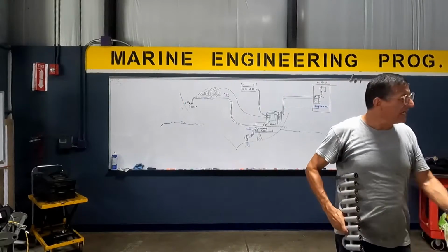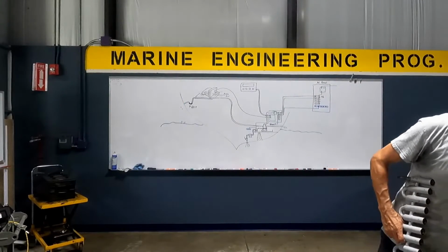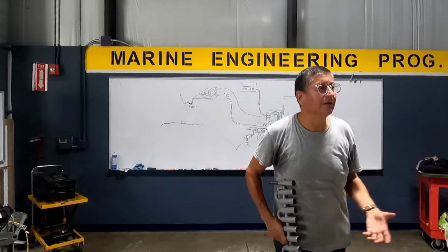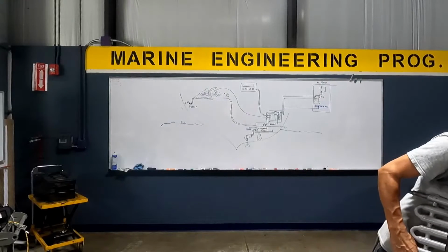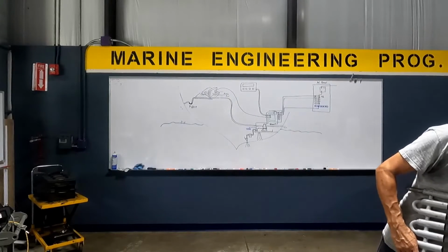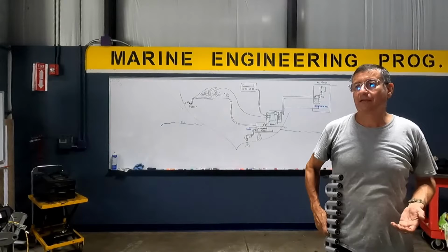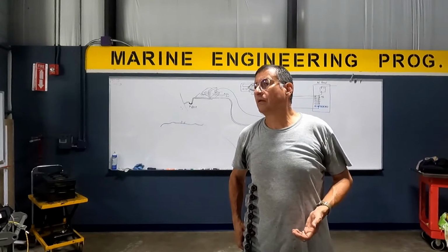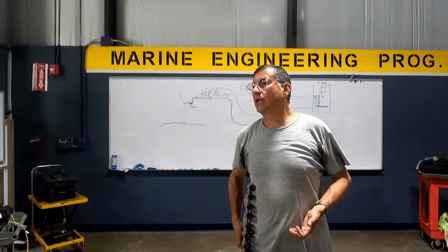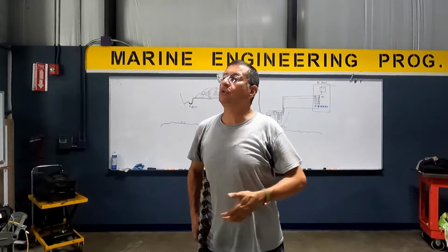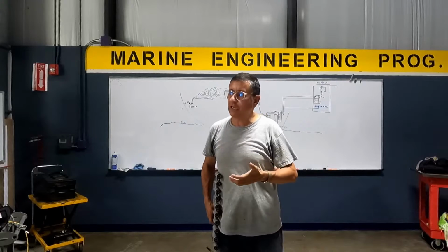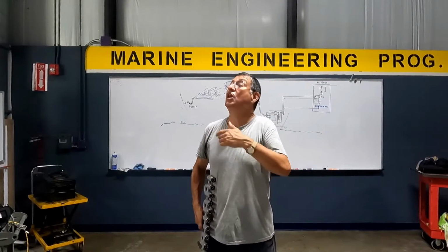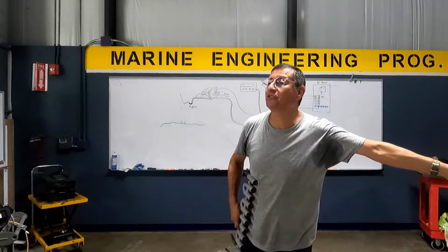Some people say, why can't I replace that dryer? Because that dryer absorbs a lot of humidity. Why is it sealed? Why do you need to cut the pipe here, install the new one, solder in the pipe? This is complicated. Like if you had a system that had a lot of humidity in it, wouldn't you need to replace that line too? Because the dryer will be overwhelmed. No, the procedure to eliminate the amount of humidity is with the vacuum pump. The vacuum pump absorbs all the humidity, including the humidity in the hygroscopic substance.